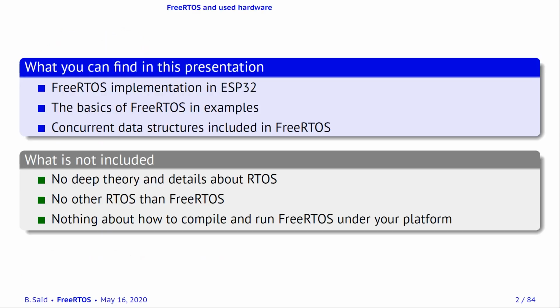You can find several examples that are using the FreeRTOS implementation in the ESP32 microcontroller. These examples show you the basic fundamentals of FreeRTOS. In the end of this presentation, we will talk a little bit about concurrent data structures that are included inside FreeRTOS. This presentation doesn't include any details and theory about real-time operating systems, and we are not going to talk about any other real-time operating system than FreeRTOS.